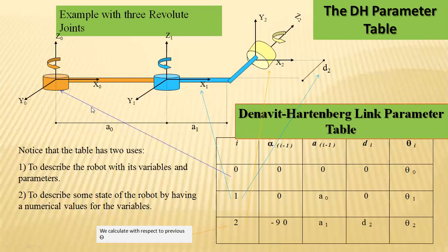First we will follow joint number, sorry, zero, the base joint. At zero, is there any orientation? There is no orientation here, but rotation is possible, and hence, since there is no orientation, we simply take it as zero. And the distance: the joint already exists in the base, so there is no length from the base, hence we assign zero.